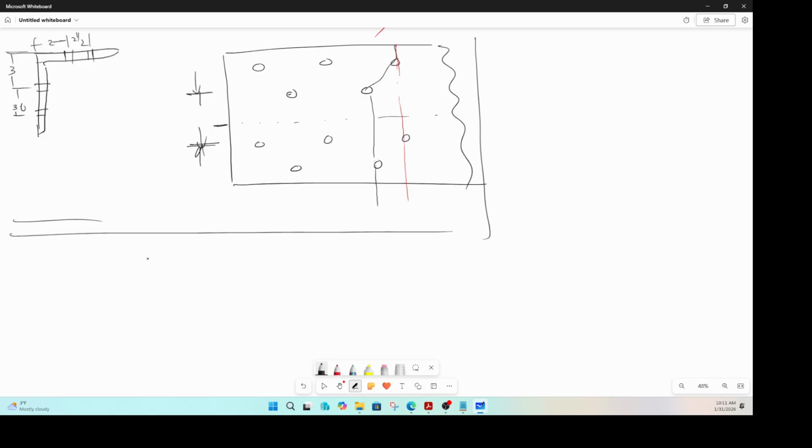It is pretty detailed and involved, and there are certain rules to see how you can figure out a path or the critical failure plane. Again, the idea is to find out your A_net given the A_gross. A_gross minus something. How you calculate that something is a little trickier when you have staggered holes like this.